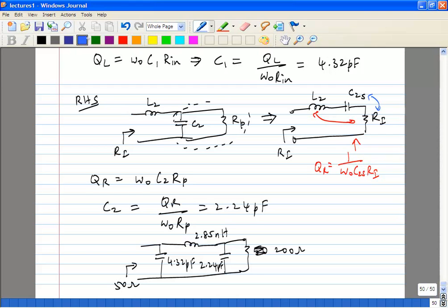So you might get a case, when you go into design an LNA or something like that, where you'll be given a band it needs to match over. I'll give you an example. Say you're designing for wireless LAN. You have a certain band, 2.405 to 2.485 gigahertz. That's your bandwidth. So your LNA in the receiver should be well matched in this band. You can't go ahead and say I'm matched outside, because then you'll be picking up stuff from other bands, nearby bands. The advantage of having a narrower response is you get some suppression of signals out of band.